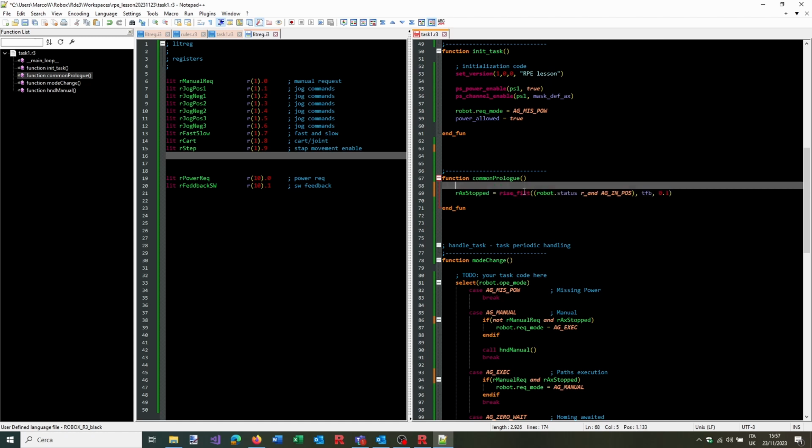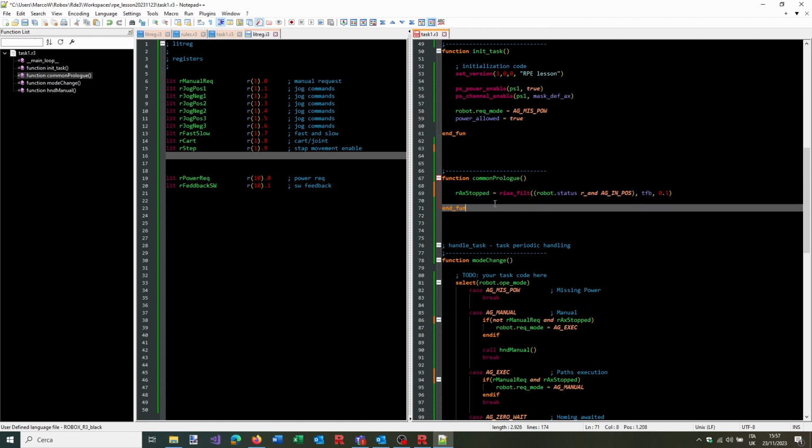So, rise filter means I want this condition to be true for the variable, which is time, but I can also use a position, an IP, or something else. In this case, I want this variable to always see this one true for this length.